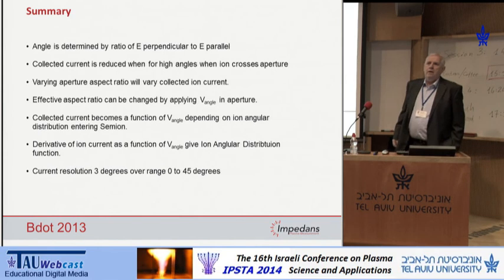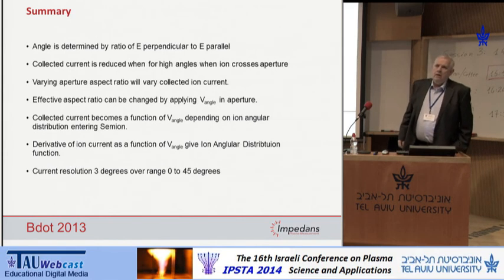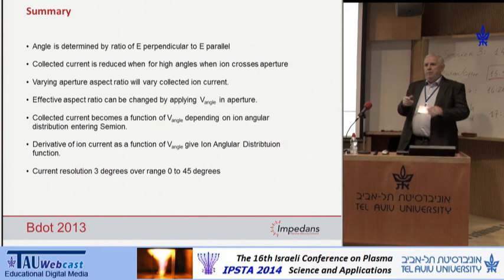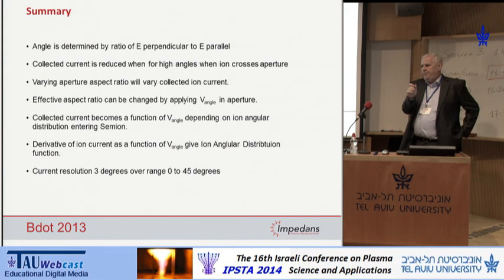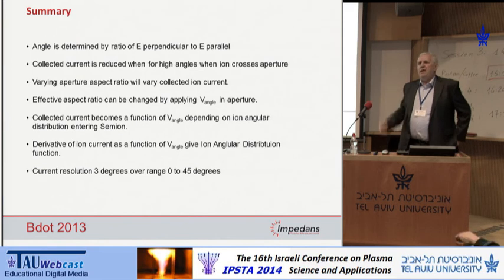So you will have some electrical penetration inside, but that usually depends on the ratio of the distance between the grids and the grid width. So the grid's aperture is 20 microns, and the spacing is about 200 microns, and that will give you about a 1% saddle in between the grid spacings. So that can be calculated fairly easily.